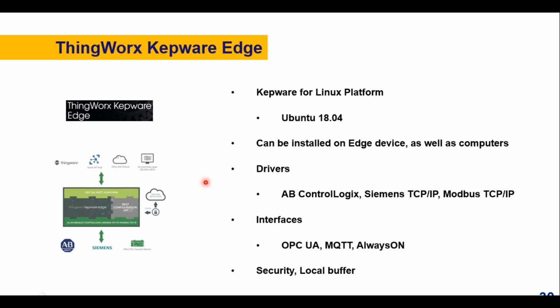So this is the latest software which you can also try using. Even though there are only 3 drivers as of now, in coming versions they will keep on increasing. The main agenda is that after maybe a few months or years, this will have more drivers, though not equal to KEPServerEx. It will have multiple drivers which will help you install multiple edge devices within your plant. That can be a good architecture for avoiding big servers or big networking costs within the plant. So that can be achieved with the ThingWorx Kepware Edge.